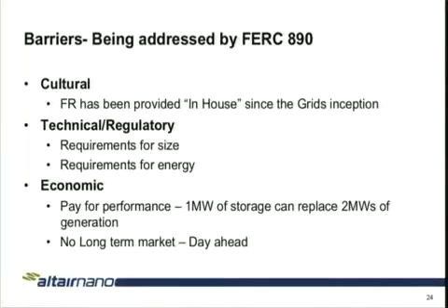We have a technical approach. It seems to be cost effective, but initially, this service was provided only by generation. That's how the grid started. Just have some extra power there. We'll just let the generators run up and down. And as we've come into this deregulation, created these services, the very first tariffs were written, you had to be a generator in order to provide ancillary services. Well, that was silly. So FERC created, by the FERC 890 ruling, said non-generation resources become available. That was good, but there were still technical barriers to size and to energy content. And those have been moved away.